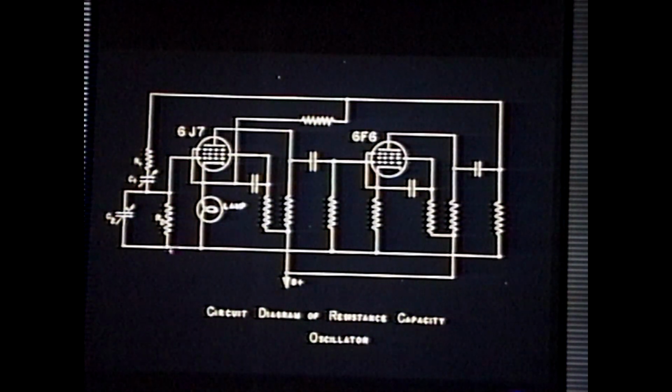If that's the Wien bridge, we know that's got to be positive feedback. There's the output here. So positive feedback through the bridge is to the first grid. The gain stabilizing feedback, where's that? Well, here's the lamp right there. The gain stabilizing feedback is also from the output back to where? The cathode. That's feedback to a low impedance node. That's current mode feedback. So Hewlett beat all the guys in the red rag by at least 50 years.